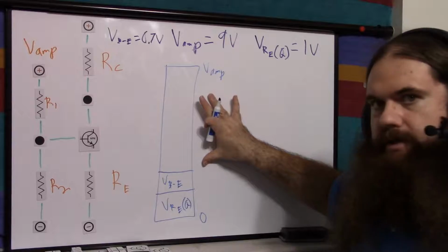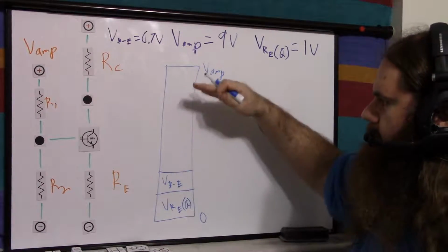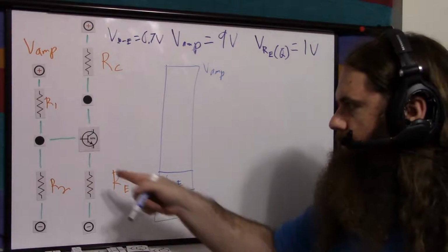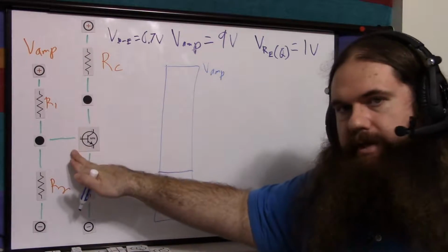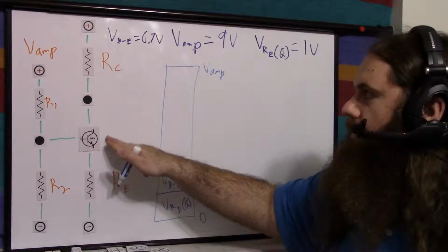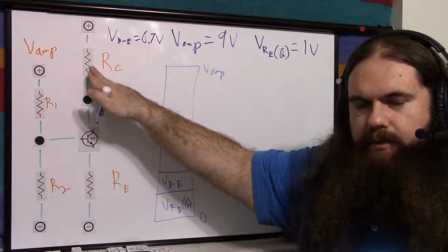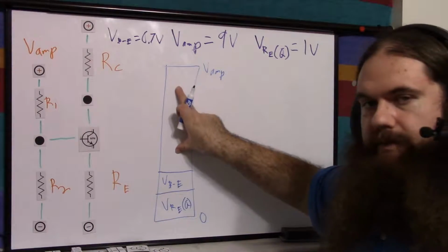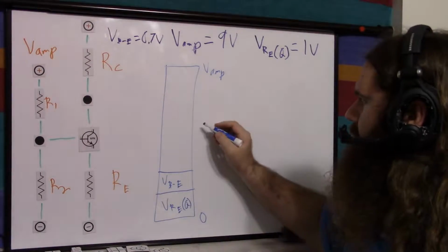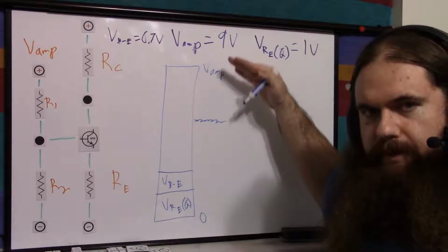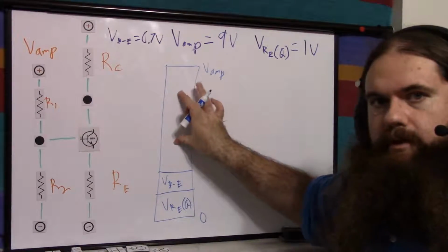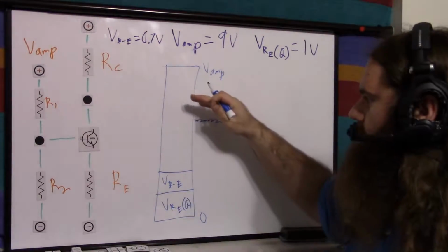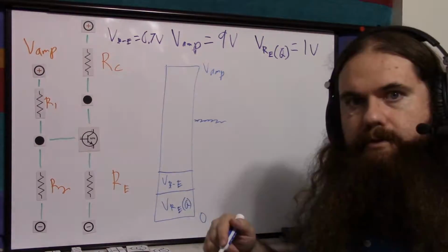So basically this is our headroom. This is the amount of voltage room the transistor can go up and down in response to the current, because the base current determines the collector current, and the collector current by V equals I times R determines the voltage drop across this resistor. So at quiescent, we have this much room. Now, quiescent is the middle. We want to go up from the middle and down from the middle. Putting it in the middle of the room we have gives us the best available space so that it never bottoms out or shoots off the top.